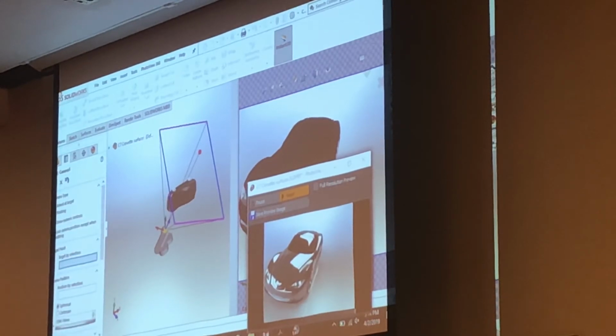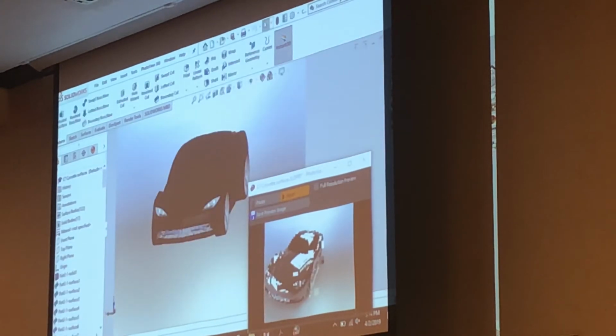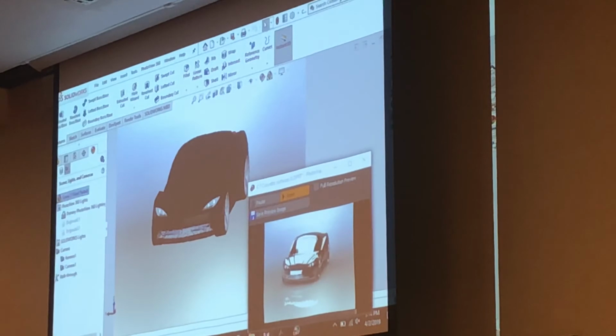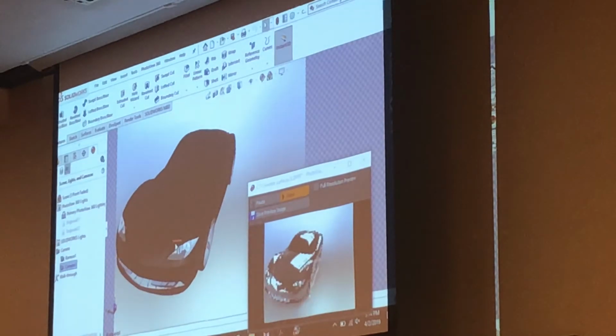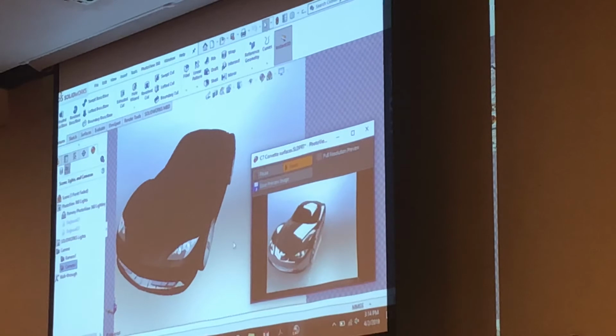Okay, if you define your camera lens and when you click the green check mark, it looks like you lose the effect of it, which often happens like that, what you can do is go to the Display Manager tab of your Feature Manager, go to that camera, right-click on the camera you defined, and choose Camera View. Okay, so that just tells SolidWorks to make sure that camera is displayed in your photo view image.